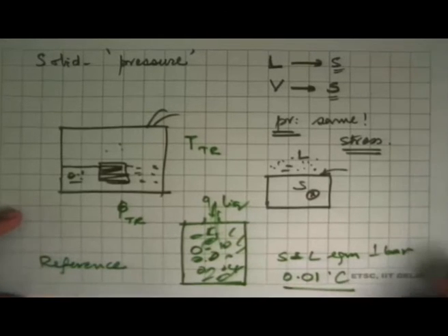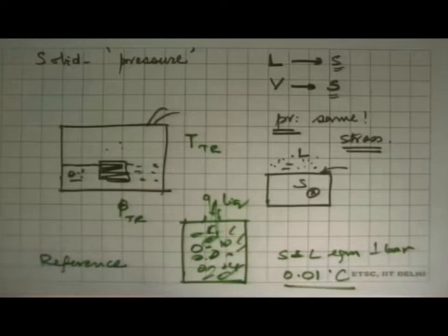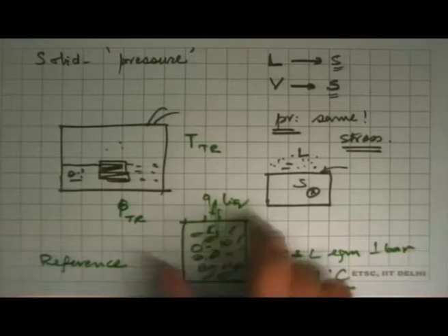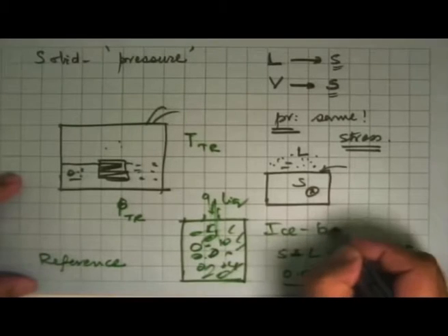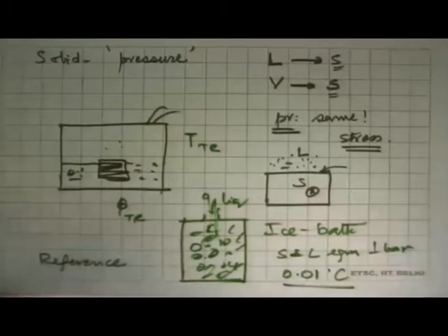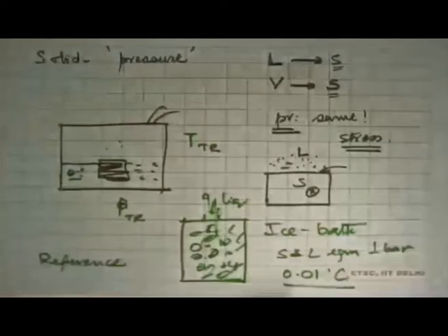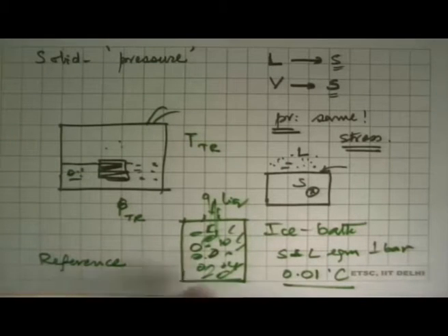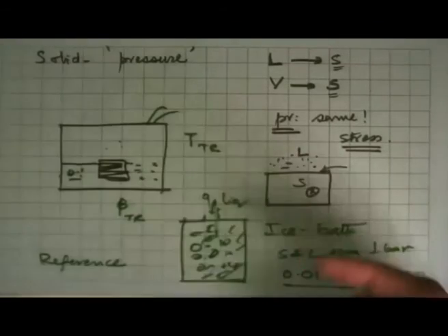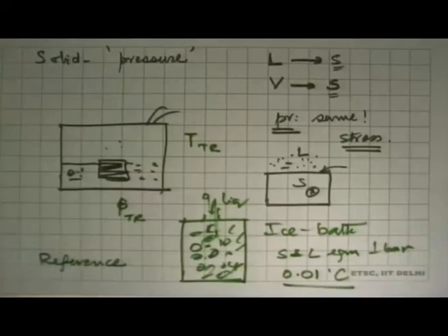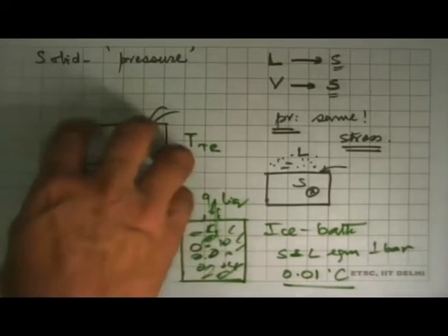Because any instrument with a thermocouple or an RTD will always require a temperature against which you measure a change in a property. Triple point with this is what is called an ice bath. This is a simple and an extremely reliable way of generating 0.01 degrees Celsius. You have in equilibrium solid and liquid. The vapor was at 1 bar, but that doesn't matter too much once you have closed it. Okay? So that's how they exist in equilibrium.